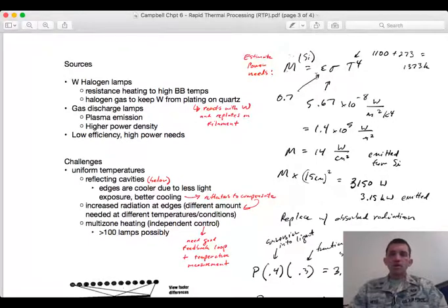So here I'm assuming that radiation from the silicon wafer is the dominant heat loss mechanism. So it's becoming a black body of its own. This is assuming that there's not a really strong convective flow within the chamber, and also that it's thermally isolated, so you're not going to get a lot of thermal loss. So mostly it's just radiation from the hot silicon wafer itself. If we're heating it up to 1100 C, that's 1373 Kelvin, so we'll plug that in for T.